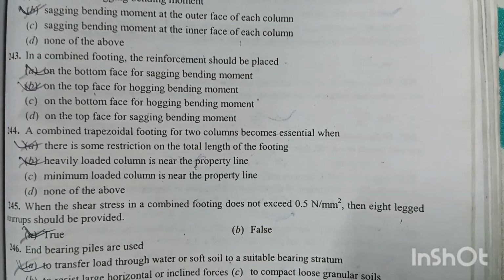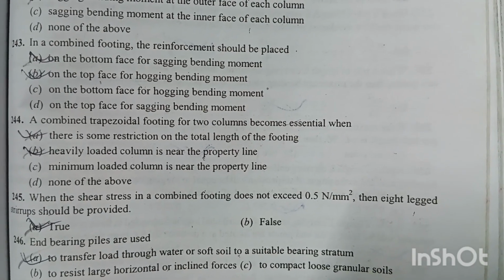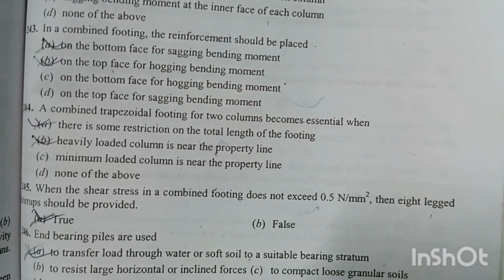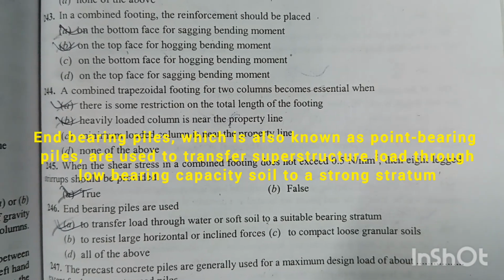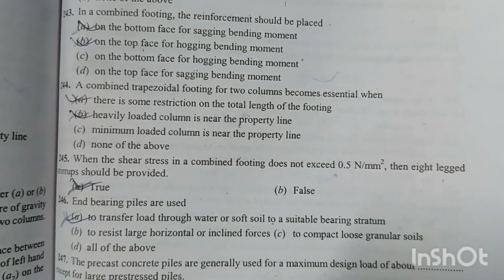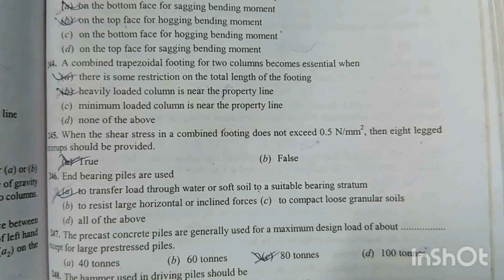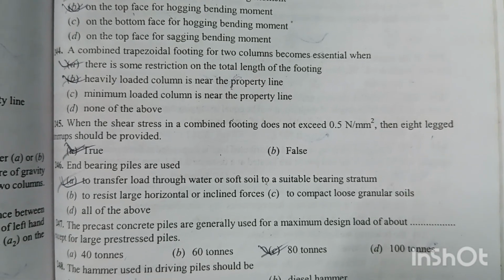Question number 245. When the shear stress in a combined footing does not exceed 0.5 Newton per millimeter square, then no shear reinforcement should be provided. Option A is the right answer, true. Question number 246. The end bearing piles are used: Option A, to transfer load through water or soft soil to a suitable bearing stratum. Option A is the right answer. Question number 247. The precast concrete piles are generally used for a maximum design load of about 80 tons except for large pre-stressed piles. Option C is the right answer.